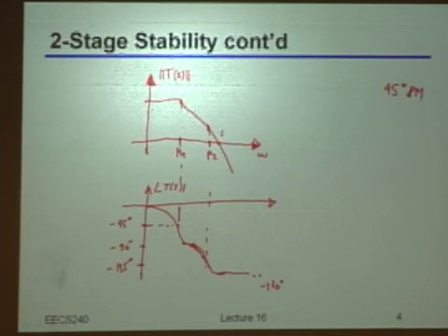Where should the crossover frequency be? Right, the crossover frequency should be placed at the spot of the second pole.